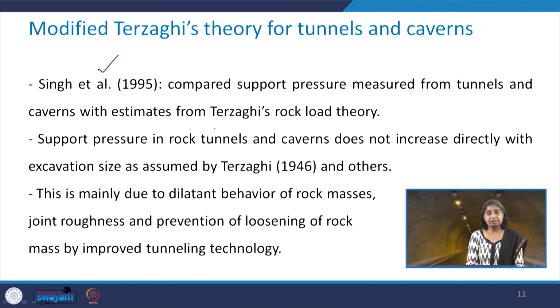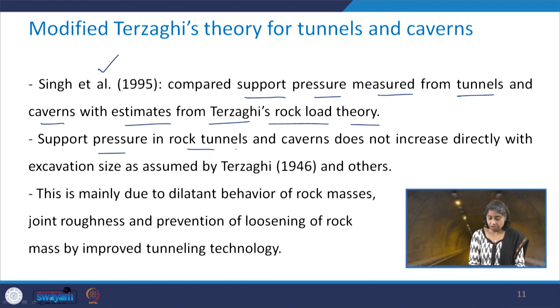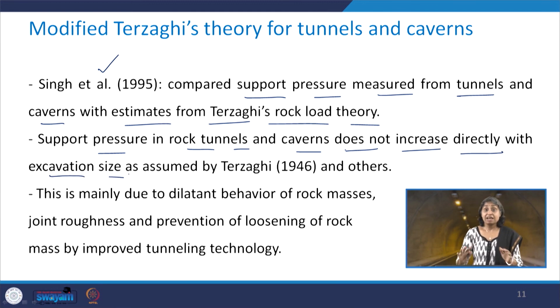They compared the support pressure measured from tunnels and caverns with estimates from Terzaghi's rock load theory. Support pressure in rock tunnels and caverns does not increase directly with the excavation size, as it was assumed by Terzaghi in 1946 and some subsequent studies.